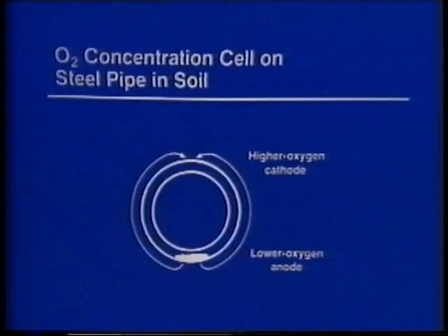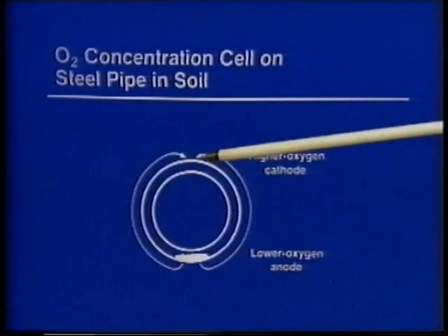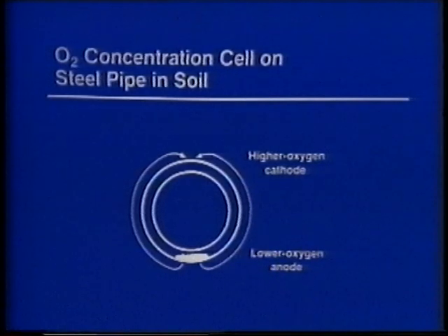So one of the things that we look for on pipelines or buried steel tanks is if we have exposed steel at top and bottom, we find the possibility to set up a corrosion reaction driven by the potential difference between the high oxygen and low oxygen area.